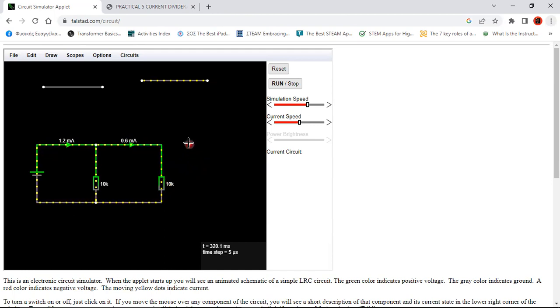As you can imagine now, what will happen to the current? I'm going to explain you a couple of things. According to Kirchhoff's law, I is equal to I1 plus I2. Imagine that this one is I. Here I have I1 maybe, and I2 here. Okay. As you can see, I have 1.2 milliamperes incoming, and I have here two outcomes.